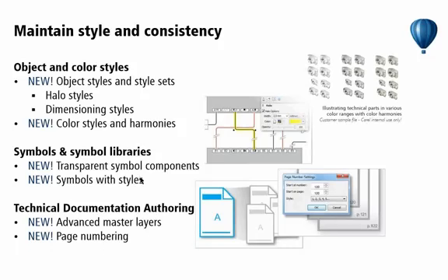The symbol libraries I touched briefly with Corel Connect, and there's also new tools that help creating technical documentation, so beyond a one-page illustration in Corel Designer. As you see in my presentation document, it's a multi-page document. You can create your technical documentation as, I don't know, maybe 20 pages single manual chapter or things like that with Corel Designer, using master layer functionality to keep elements like the balloon in my presentation on all pages. New with options to create even and odd pages in a different layout to master these tasks for creating multi-page technical documentation.